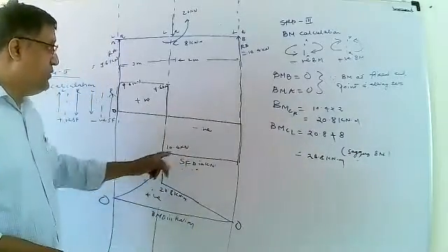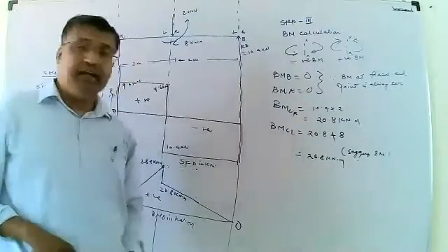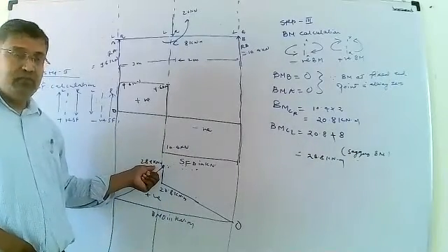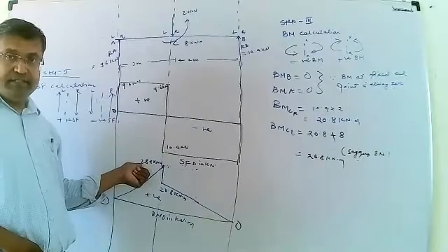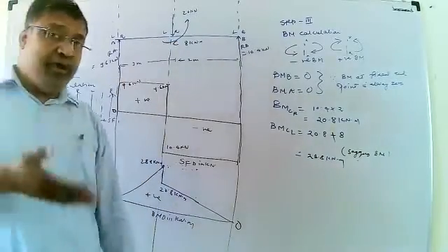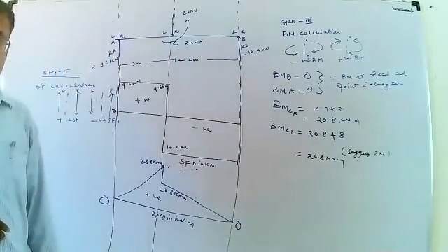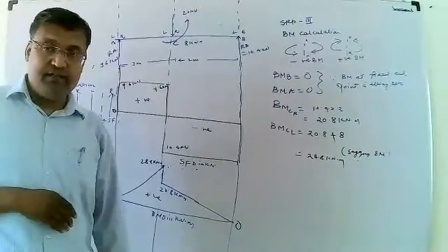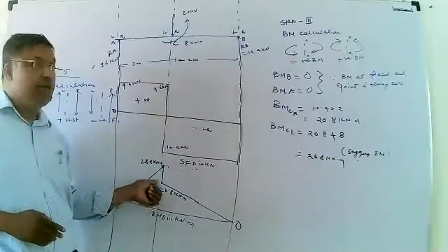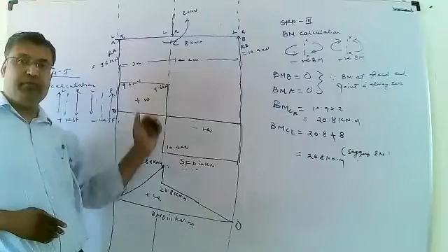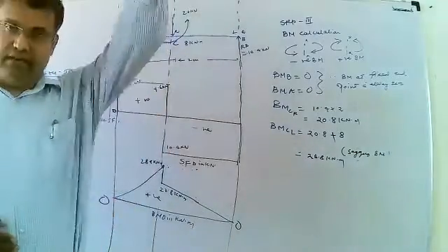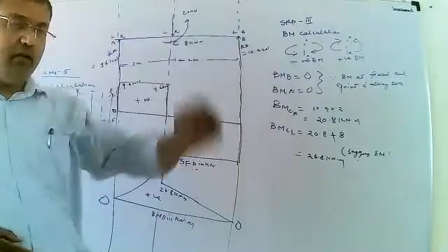Then you see that value on the left side is 28.8, so you write that value at the point C on the left side. Then the moment is anti-clockwise, and if the moment is anti-clockwise, then that line will drop. Okay, if this moment is clockwise, what will happen? The line will go in the upward direction. The line will rise. Clear?